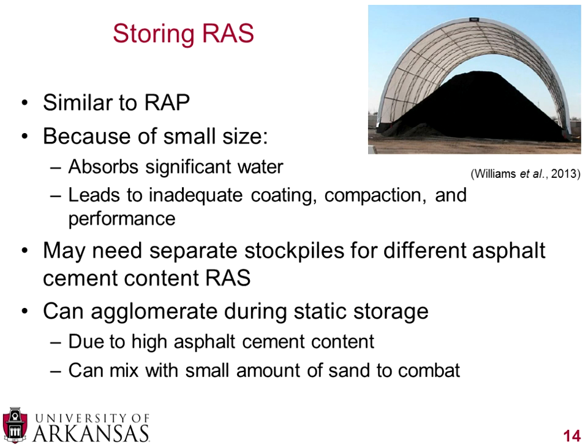The final step of processing RAS is the storage of RAS, and it's very similar to RAP, recycled asphalt pavement. However, because of the small size, it does absorb a significant amount of water. Just less than 1/2 inch, possibly less than 3/8 of an inch, really does lend it to absorbing water. And if you have water in your RAS and it goes into the asphalt concrete mixture, that can lead to inadequate coating, compaction, and poor performance.